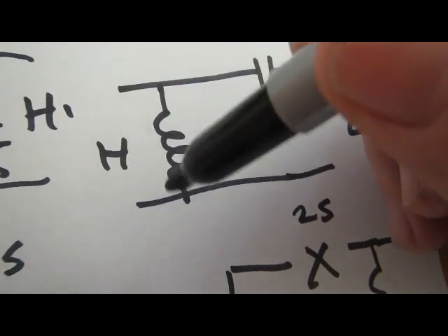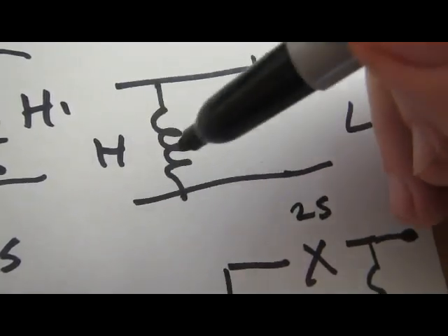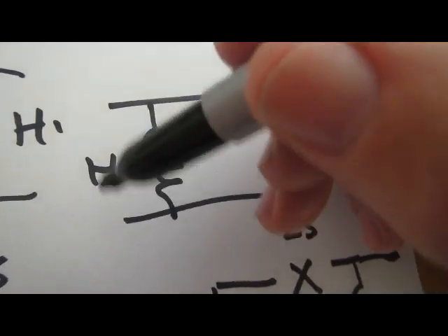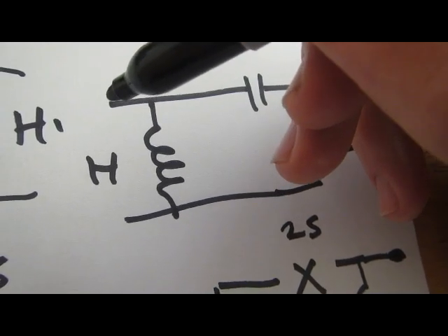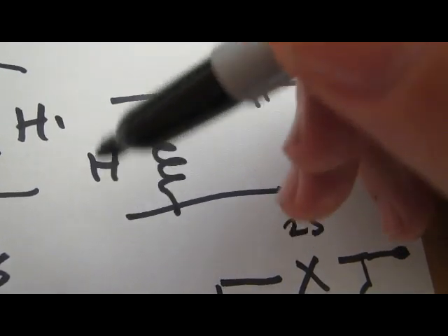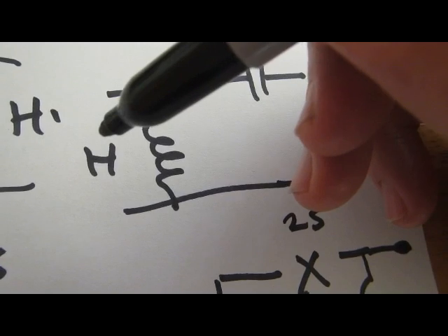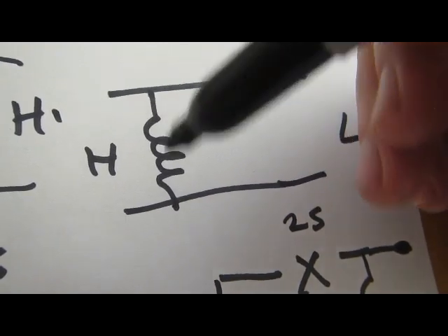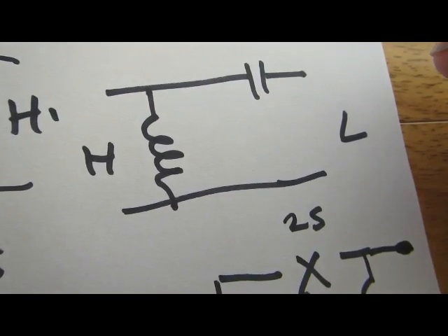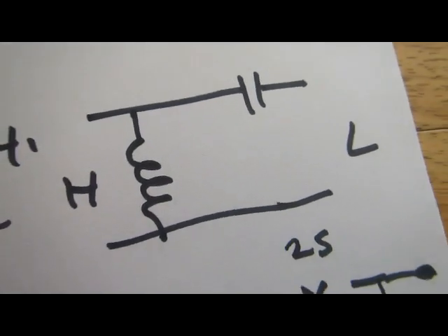Because when we're mopping things up with parallel, we need other things in parallel, so we can use our parallel circuit to do it. So if the L network starts with a parallel shunt element, and the load is reactive, we need to express the load with two parallel elements, X and R, so it can be mopped up with that L. That's what you have to do. Then it gets a little bit more complicated, but that's what you have to do.